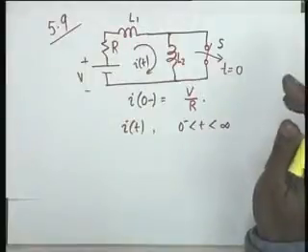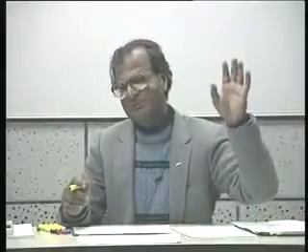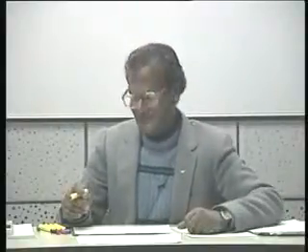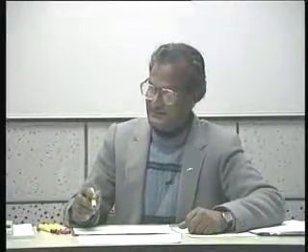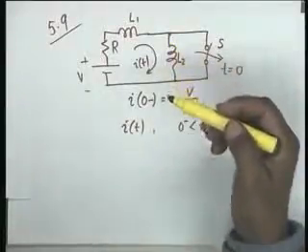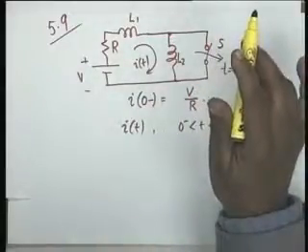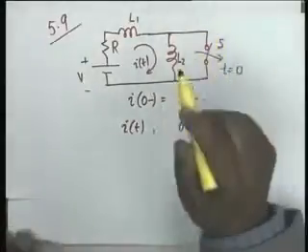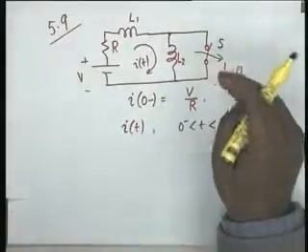But at t equal to minus infinity, when the switch S was thrown, it was closed, then there would have been no current in L2. Since it has been shorted, there will never be any current in it. All that was infinite time ago. But since then, sir, the current has been flowing through the short switch only, not through L2. But L2 also provides a short. Short only if initially some current goes. No, this is a degenerate situation again, because it is being shorted, because a switch is being thrown open.